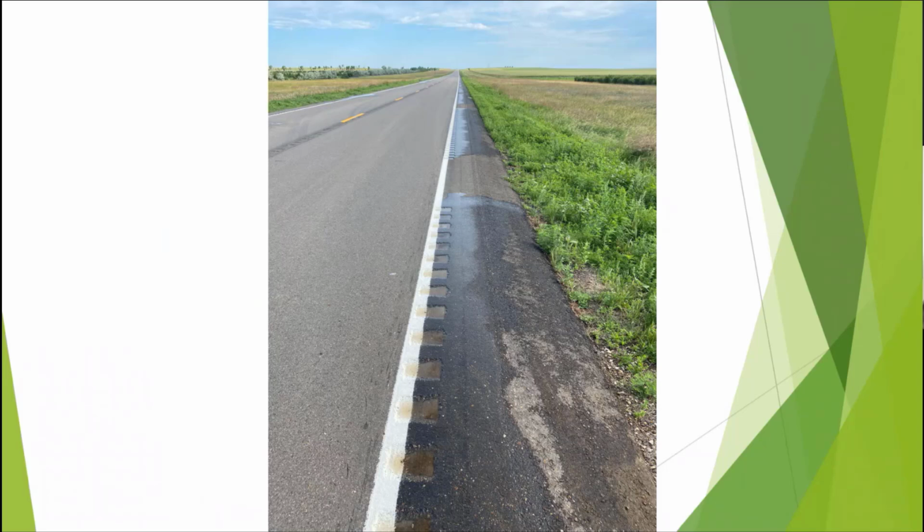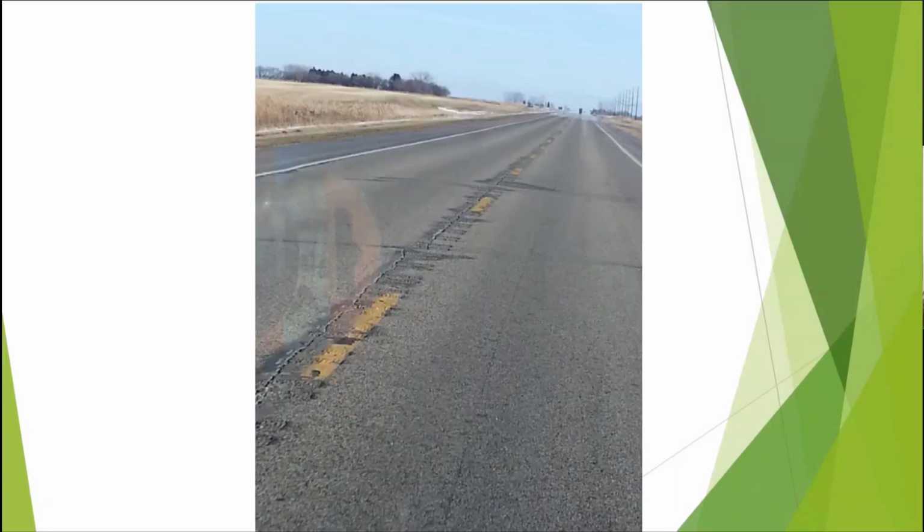What's happening to all that water? If you got a lot of air voids in that area, where's it going? It's not going out and daylighting out to the edge of the pavement and into your borrow ditch. It's going into your pavement, which is going to weaken that weak area already. So there's retrofitted rumble strips on an old longitudinal joint.